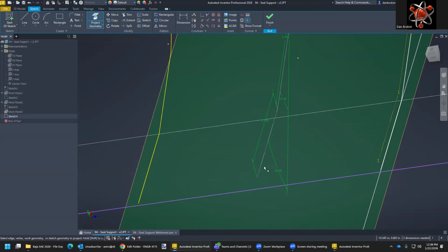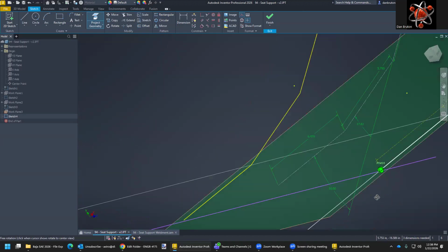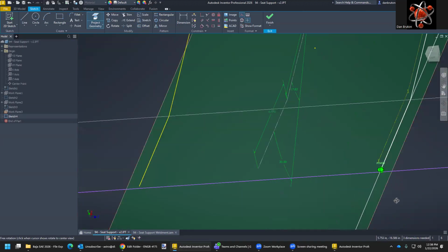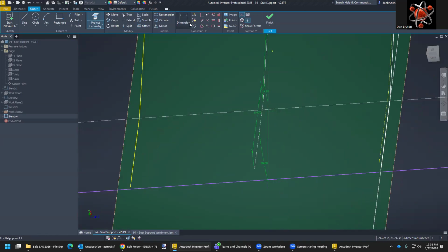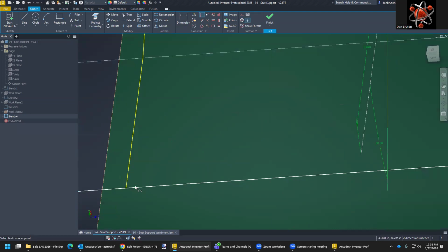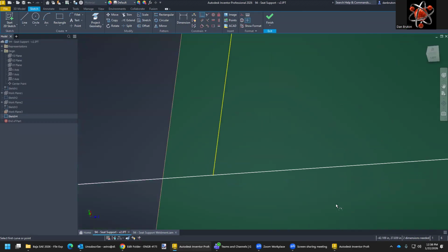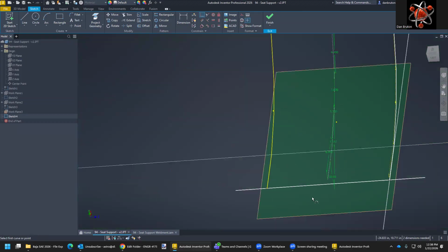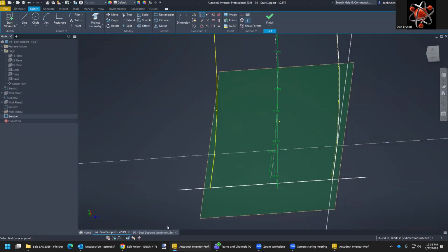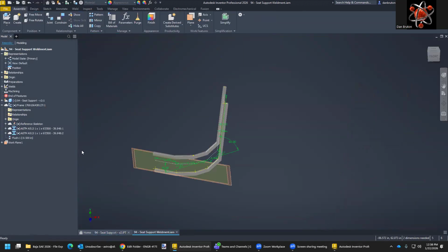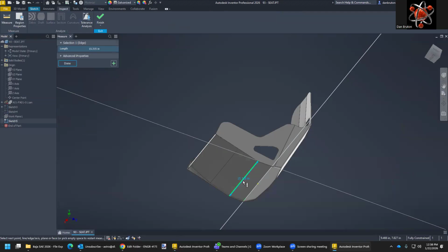Is that what this is here? No, I think that's actually the bottom of the seat, so it's a little bit different. Okay, now let's see if we can go back and do the coincident. It looks like it might already be coincident here. Oh, okay. All right, now it's coincident. Now it needs to have equal overhang across the whole thing, and it needs to be less than the, let's see, 15.35. So we'll just make it 15 so it fits snugly under there.